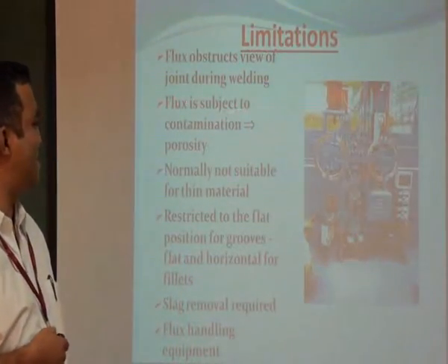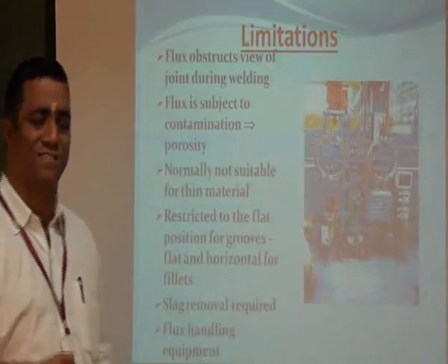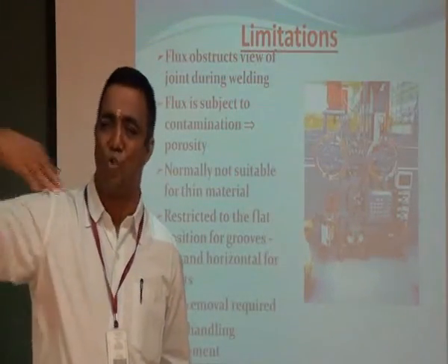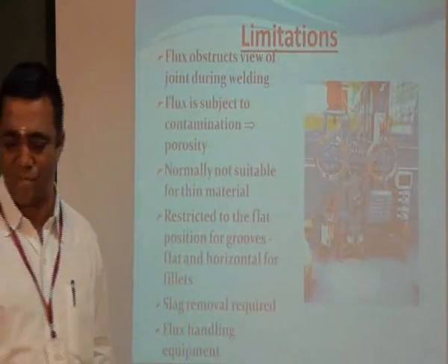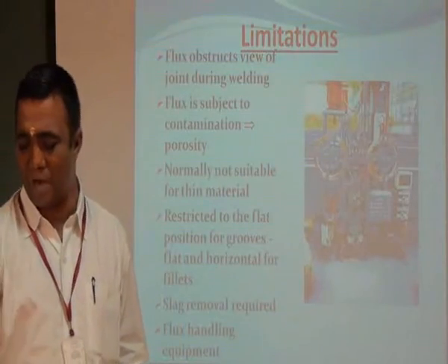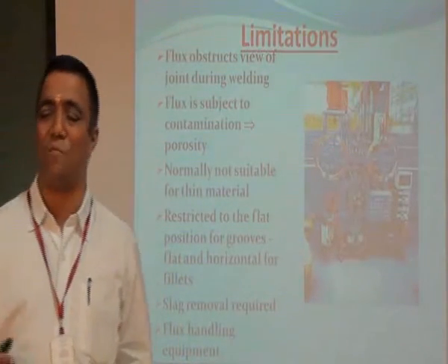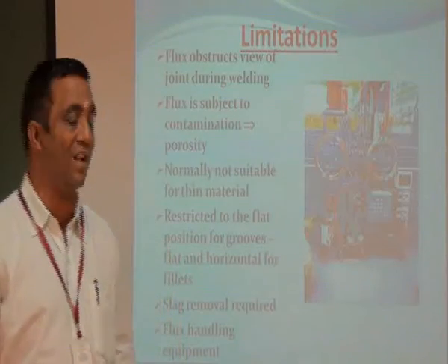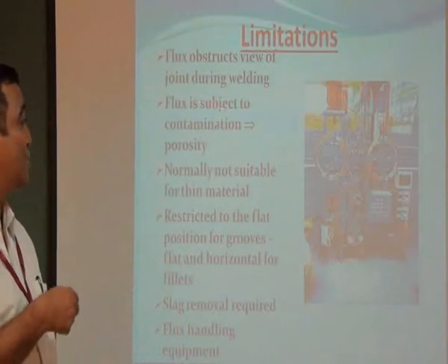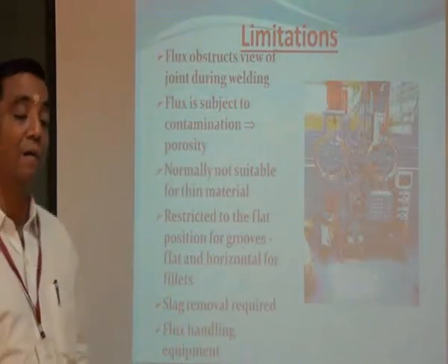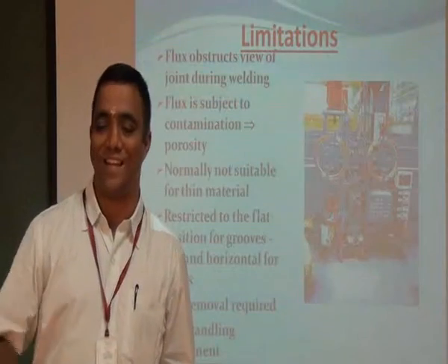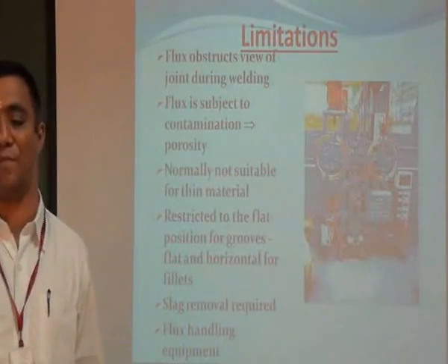The next limitation is that the flux is subject to contamination when exposed to the atmosphere, because flux is spread only on the base plate surface. It will absorb moisture and is subject to contamination. So you have to use only carefully reclaimed flux. It is called reclaimed flux.